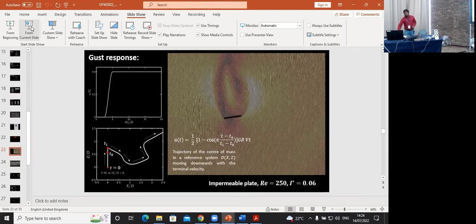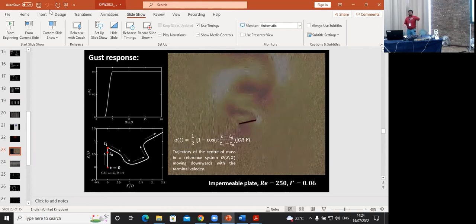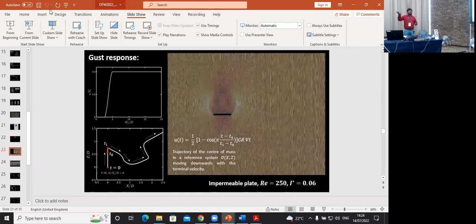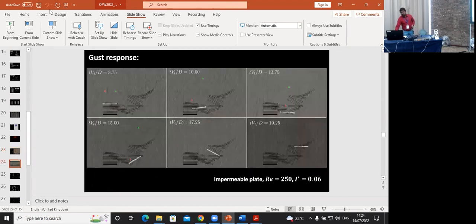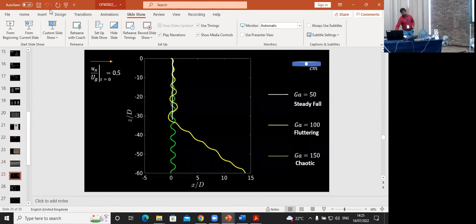And we see that slowly this vortex ring gets distorted and gives rise to a very nice vortex shedding, and we basically see the plate with the leading edge and the trailing edge vortex, which gives sufficient lift to the body to keep itself afloat, extracting the energy from the flow. And this is the same thing, an in-depth analysis of how these nodes and saddles behave and how they change to give rise to the leading edge and the trailing edge vortex.